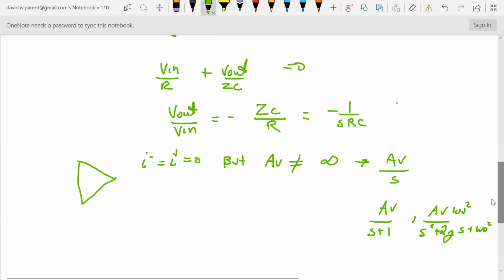Although we have talked about the power supply limitations, but on that first op-amp homework where I said there was no capacitor inside, or there was a capacitor inside, well, inside op-amps, there's a capacitor, and we have a choice of how we model it, all right? And we will model that as we go along, and it'll be a big part of the class. But a lot of times, as long as we keep our frequency within a certain range, we can assume an ideal op-amp and make our designs more intuitive and easier to understand.